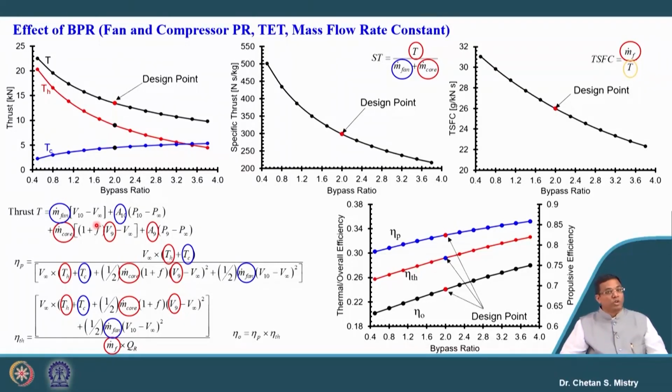So, when you are doing your calculation, you do it with pen and paper, and maybe later on you can make a code. Using that code you will be able to calculate. See here in this case, this velocity parameter is what will decide whether your nozzle is choked or unchoked. So, that is very important. You need to do this parametric calculation very systematically.